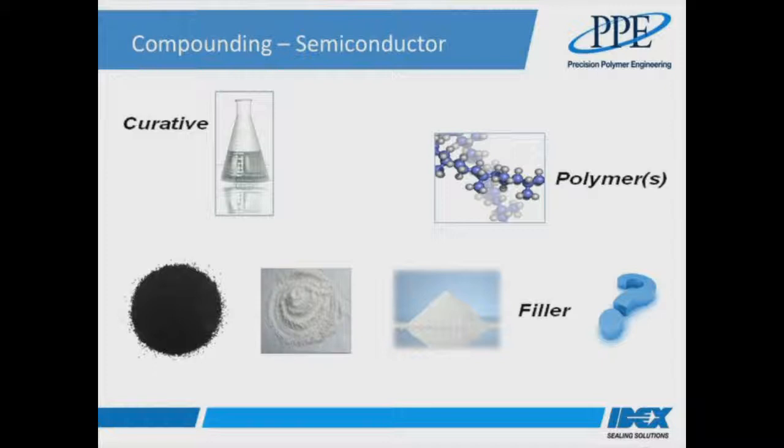And there's a good reason why they're black, and that's because a common reinforcement additive is a material called carbon black. The clue's in the name, right? Carbon black, even in small amounts, fundamentally affects the colour. And there are again many different types of carbon black. Typically, there are around 6 that are commonly used carbon blacks for elastomers. Each one provides varying degrees of mechanical strength. Different structures reinforce the rubber in different ways. Some make elastomer processing easier, others result in very tough materials, and it's possible to mix and match to get the properties that are needed.